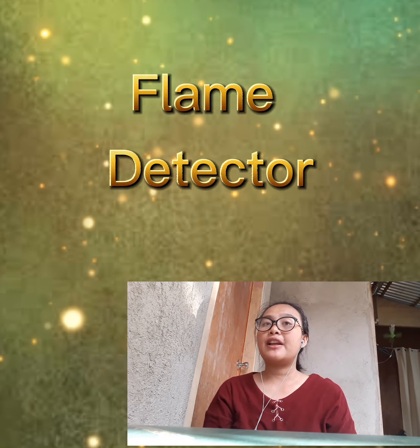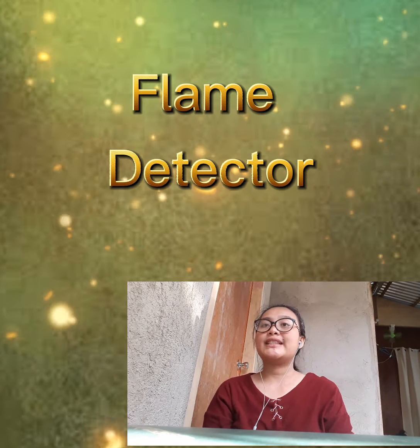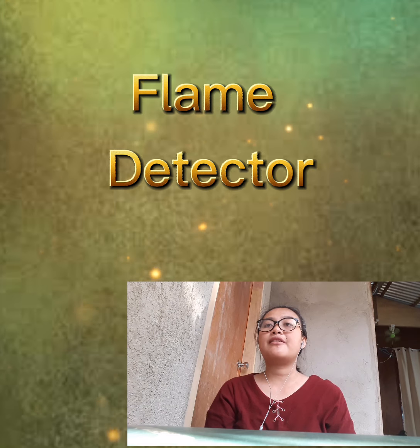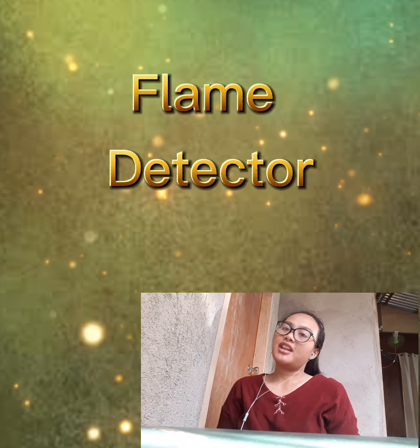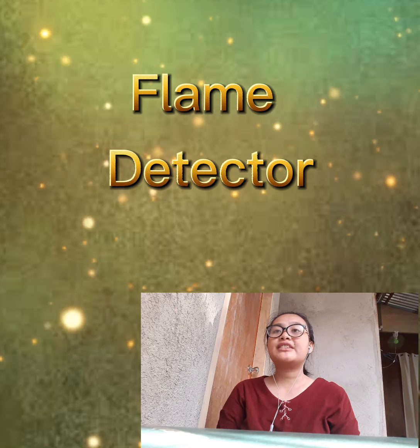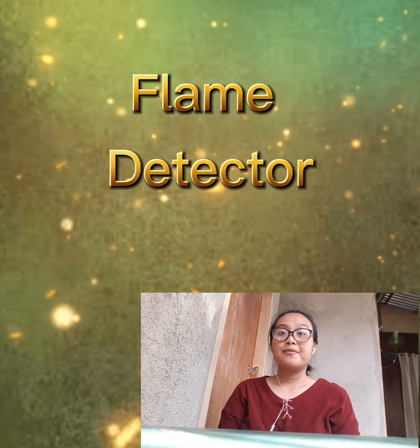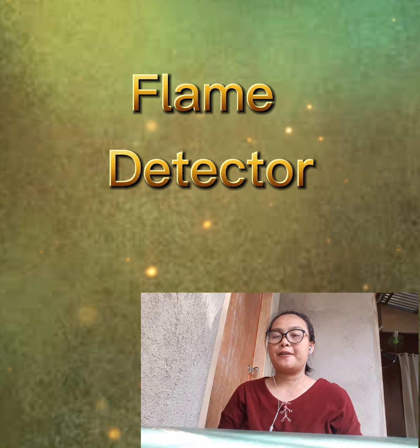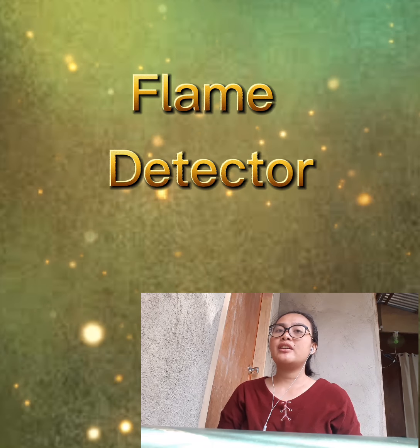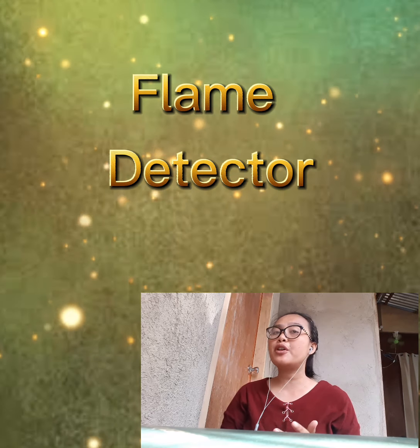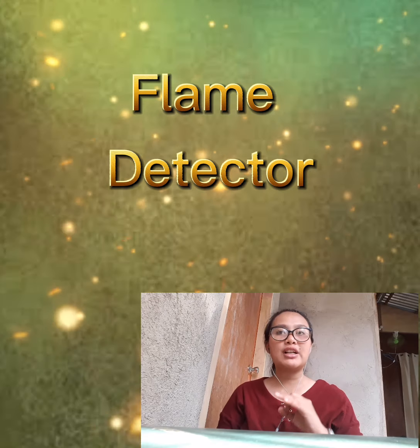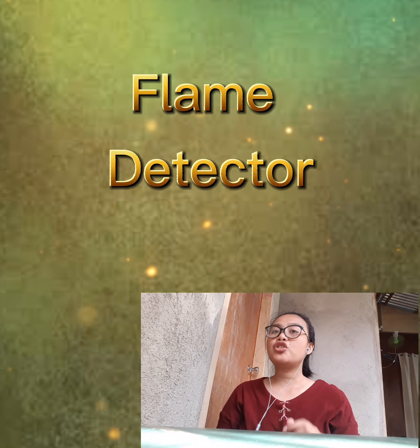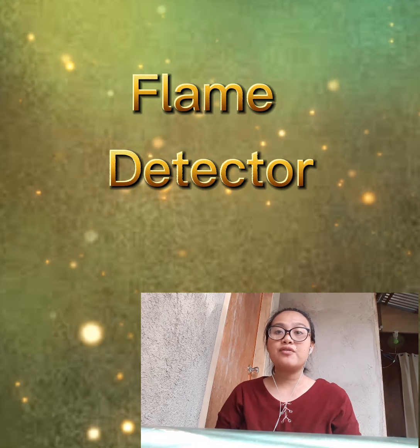The fifth one is the flame detector. A flame detector is a detector which responds to the radiation emitted by the flames from a fire. Its criteria: it shall be a combined ultraviolet infrared type, monitoring both UV and IR regions of the spectrum for the presence of fire. Also, the detector shall be resistant to operation caused by sunlight, artificial light, and black body radiation. And lastly, the detector shall have a nominal 90 degree cone of vision.